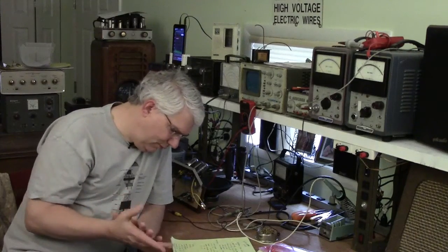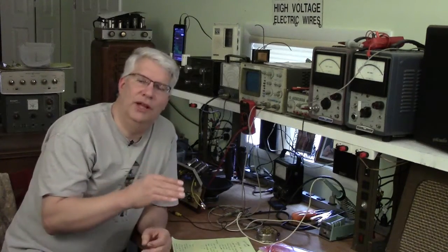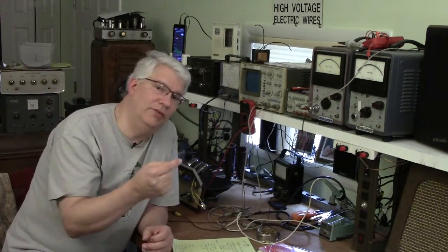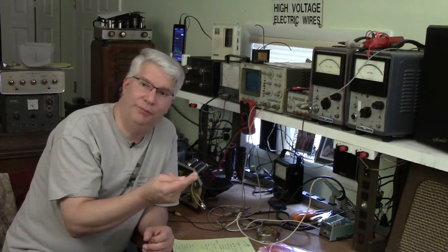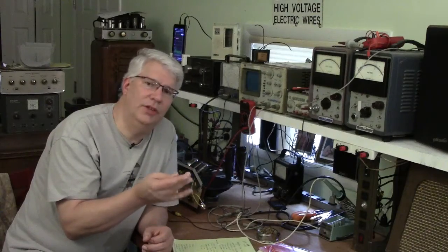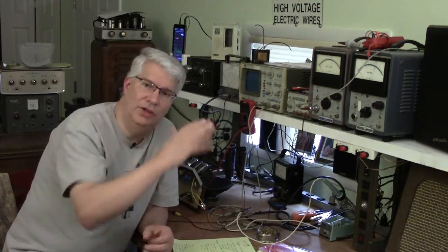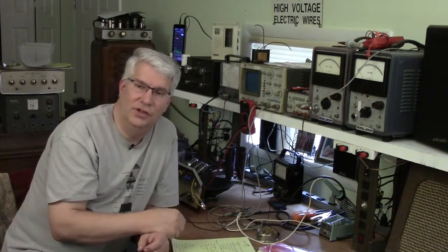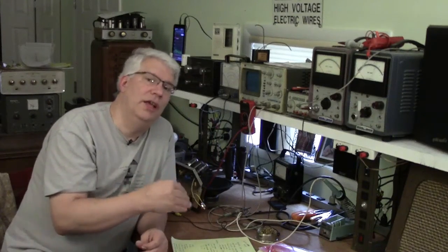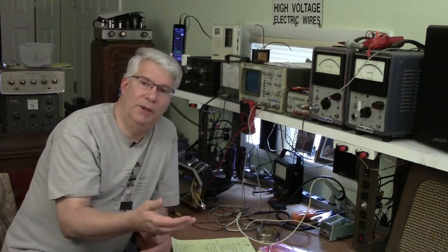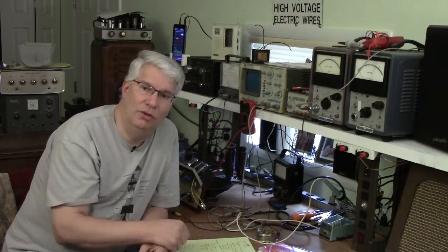Okay. Then we're going to play with the load line. Now remember, the load line in the interactive example will let you change the plate voltage. It'll let you change the plate current. It'll let you change the turns ratio and the speaker impedance. And from that, you can do a lot of different kinds of scenarios. And the interactive example also dynamically calculates the power output as well as the total harmonic distortion.